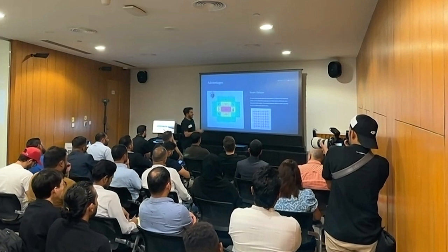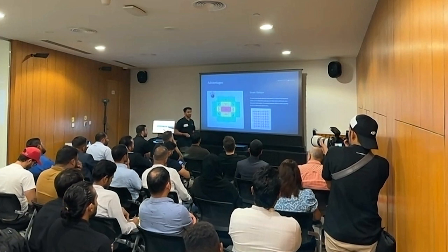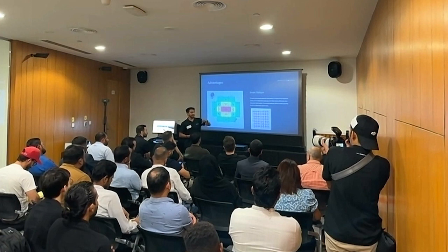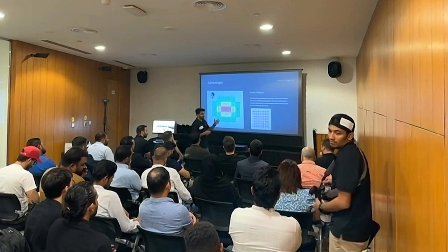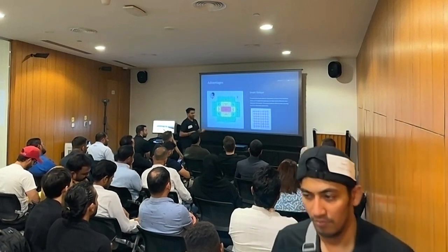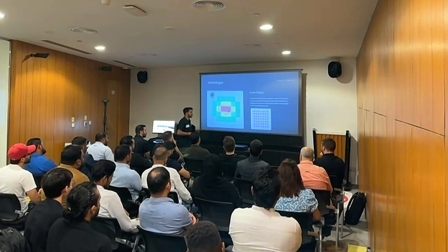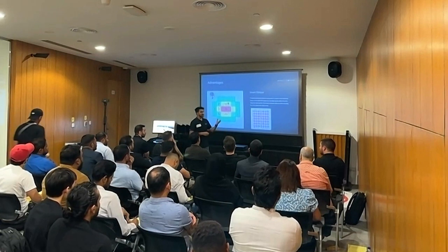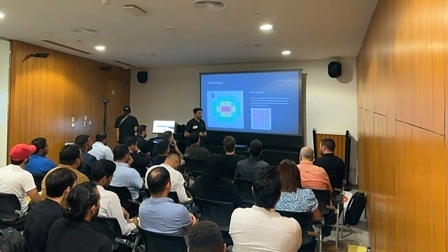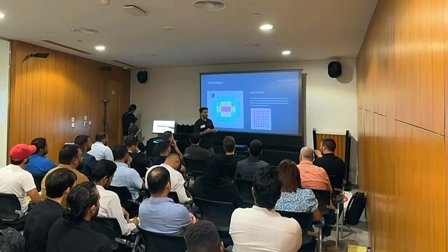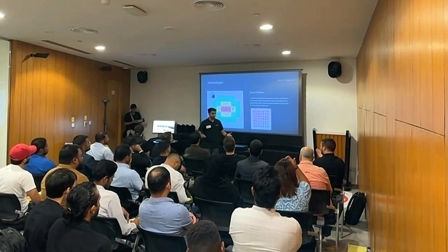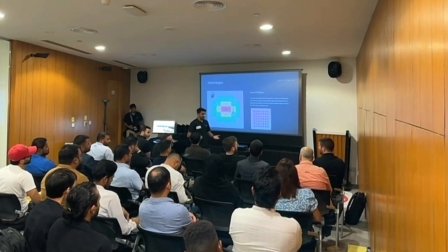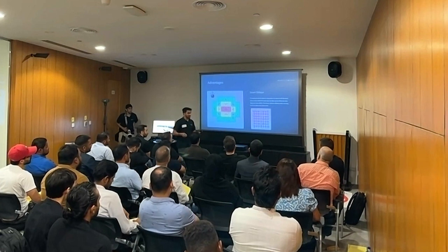Also, with the latest update to the Mavic 3, it can capture 3 different angles with Smart Oblique. The P1 can capture 5, but the Mavic 3 Enterprise can capture 3, which ensures the overall accuracy. In the other method, you might be taking 1,000 pictures, but with Smart Oblique you are reducing the number of pictures, so you can expect a 20 to 50% reduction in processing time. Yes, Smart Oblique is for 3D mapping.